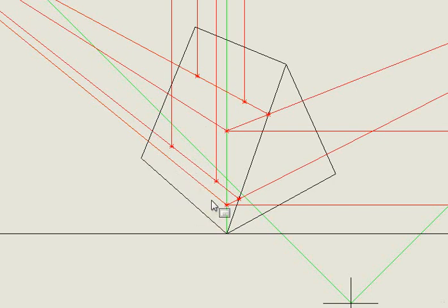So what I've done here is this information point projected back to my right vanishing point actually touches 2 areas of this gable roof or triangular prism. It touches over here on the slant edge and on that side there. Now we want to draw everything that's visible first, so we're going to be working with this one.